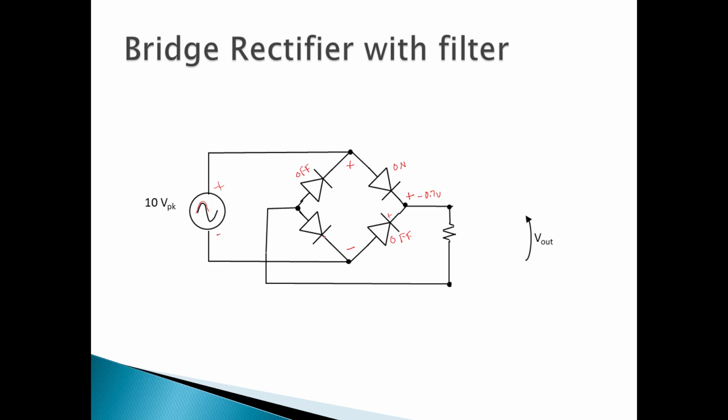Okay, let's trace it around. All we got is this one more diode to figure out what's going on there. So if we take this positive, we may get some voltage drop here. We'll get some, but basically this lead wants to stay positive. So here we come around here with the positive. So this is positive, and this is negative, so this diode is on.